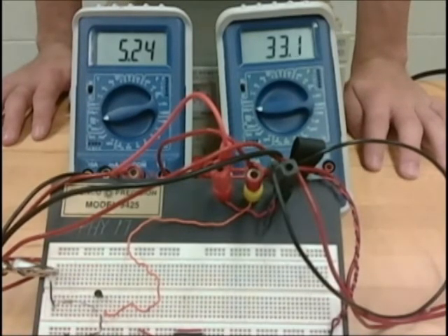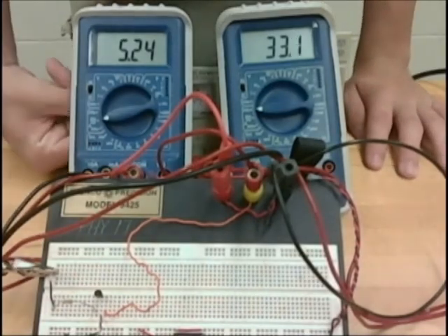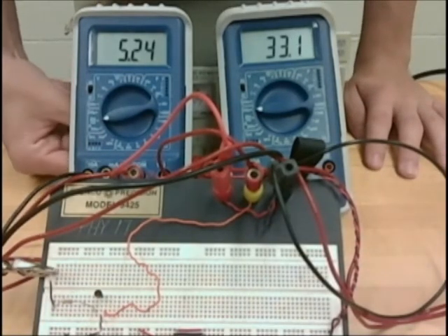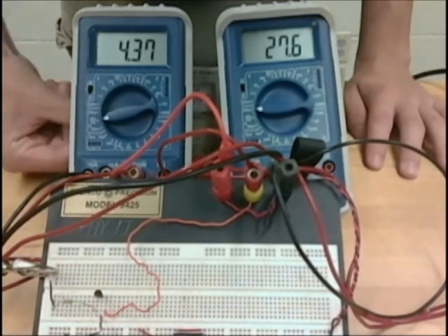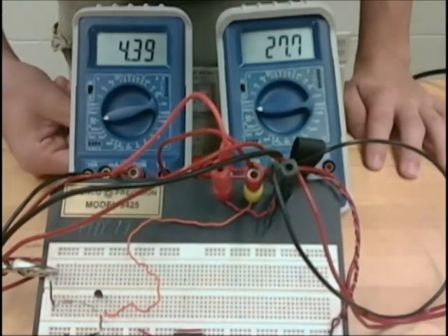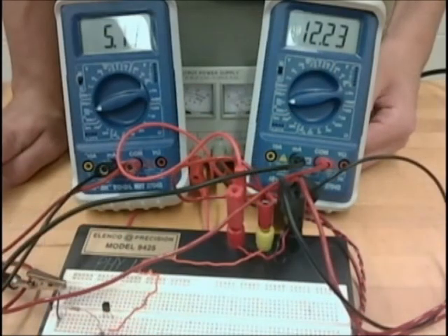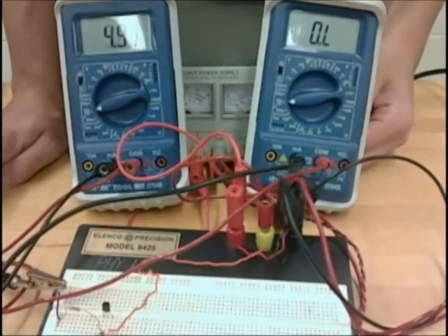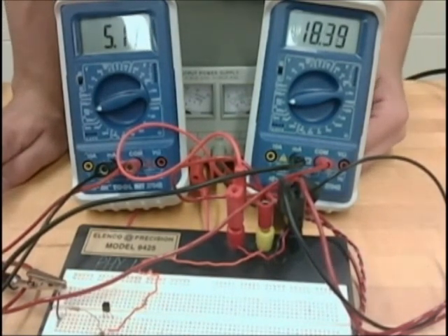After we got our first values recorded, we adjusted the voltage output on the power supply for base voltage first, and the emitter current changed proportionally to the current change through the base. Afterwards we changed our voltage supply through the controller, causing the voltage through the emitter to change, resulting in a change in our base current.